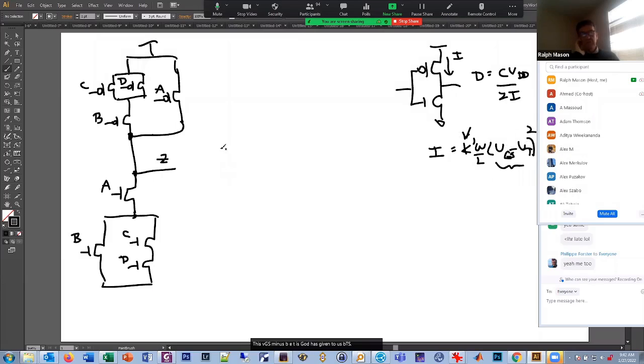VGS, for digital circuits, we're going to assume VGS is just the VDD in our case all the time, right? Because we're driving these inputs either to VDD or ground, with CMOS circuits. And we said we don't really play around with L. We always use the minimum L. So the only thing we play around with is this W, okay?